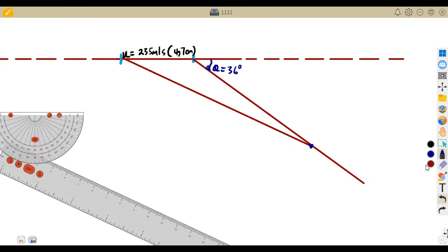So we are going to obtain a length of 13,5, meaning to say our absolute input velocity, or the input absolute velocity in this case, in terms of centimeters, we got 13,5 centimeters. So remember, our scale is 1 centimeter to 50 meters per second. So this value, we are going to multiply it by 50 to obtain the speed now in meters per second.